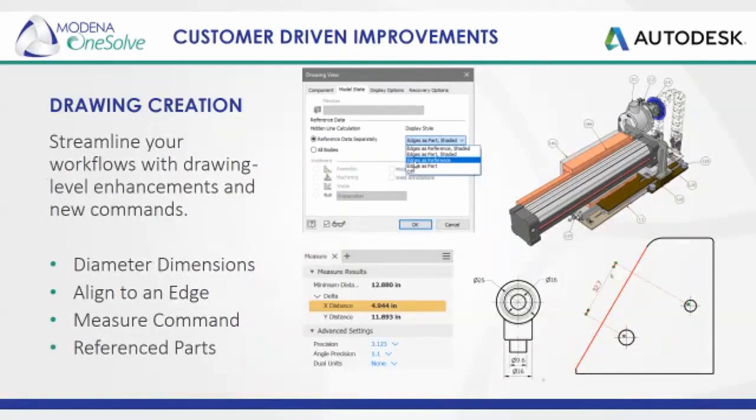A new set of drawing tools and functions have been bundled into Inventor 2021. This includes a new dimension type called parallel diameter. What this does, it creates a dimension with a diameter symbol when you select the outline edge of a cylindrical feature, such as a hole or a shaft.